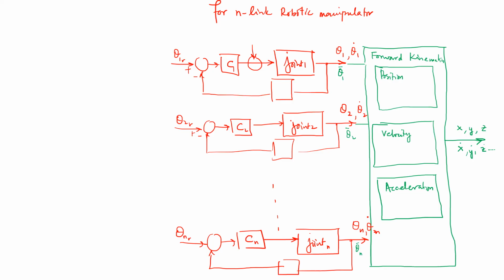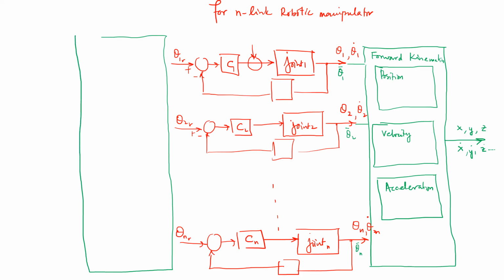Now on the left side as well, you can see that you've just written down these reference signals in terms of angular displacements, but because you have the velocity and acceleration added in, those are going to be added as reference signals as well. So these are being generated from a similar big block, but internally there are going to be quite a few different things, what we call the inverse kinematics block.